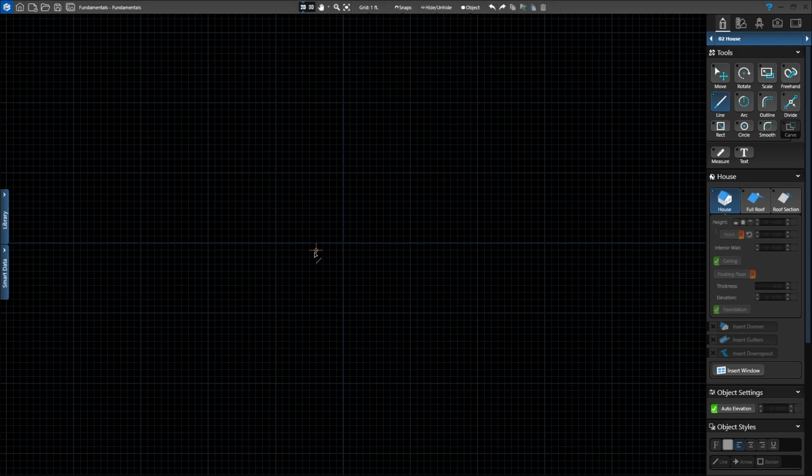To begin drawing, we'll go to the top of the panel menu to our toolbar. If you hover your cursor over the icon for the tool, you'll get a description of what that tool does, and then in parentheses you'll see a letter, and that's the key on your keyboard that will activate that tool. That's your shortcut or your hotkey. We want to activate the line tool. So left-click on the line tool, bring your cursor over into your drawing space. You'll see the little line tool icon.